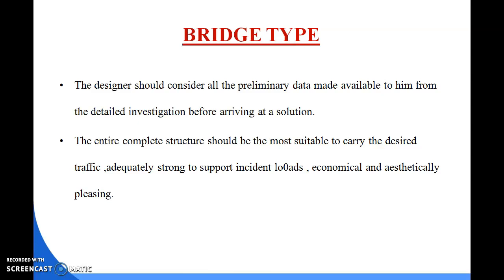Next one is the geotechnical and seismic data. In geotechnical and seismic data, we study the stability of the river, location of faults and their activities, and we also study soil classification, grain size, and the depth at which hard strata is likely to be met with. Mainly auger boring test is used to collect the soil sample and further study its engineering properties. Okay.